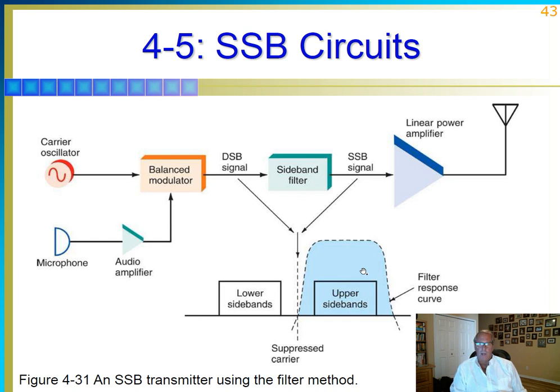That's important. I would also like you to make sure you understand the process of demodulating an AM signal using a diode detector. That's important because that's what we did in our lab, okay? And the concept of a square law function, where you can use a diode, or at the beginning of this presentation, a diode or a transistor which has a square law function to do the multiplication and the mathematics that are required to combine the carrier and the modulation signal to create a full modulated sine wave.